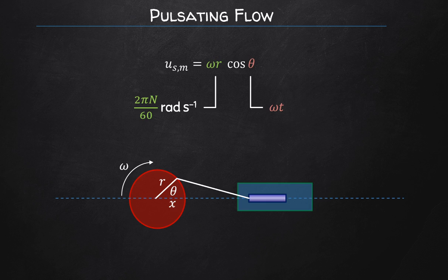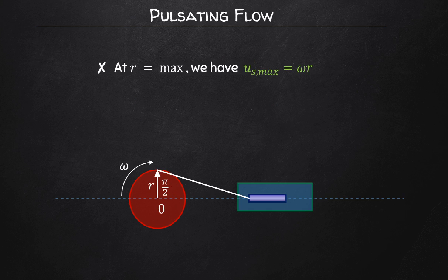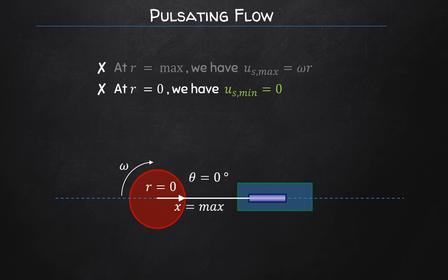Obviously, it depends on which time position you're at. When the radius is at its maximum, as measured from the plane of action, which I give you as a dotted line, the maximum velocity is obtained, while the velocity reaches zero when the radius of action is aligned to that plane of action, that dotted line. So when everything lines up on the dotted line, zero. And obviously on the other side as well, so you have two places where you're going to have a zero